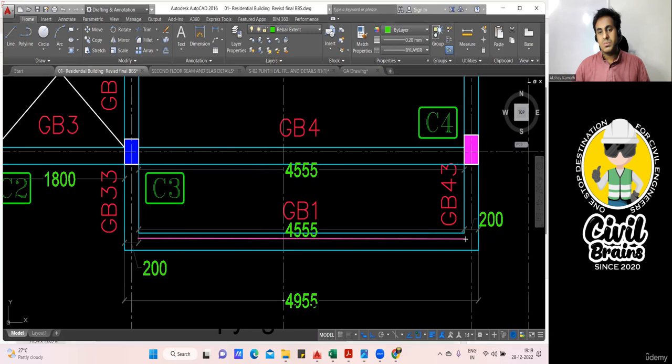This will be a straight portion of bar where the length is 455. And from here, your development length will start. It will go up to here, not completely. You'll take this length; this length will be the width of the beam minus cover. So this time, which cover do you have to take? Beam cover. Why beam cover?